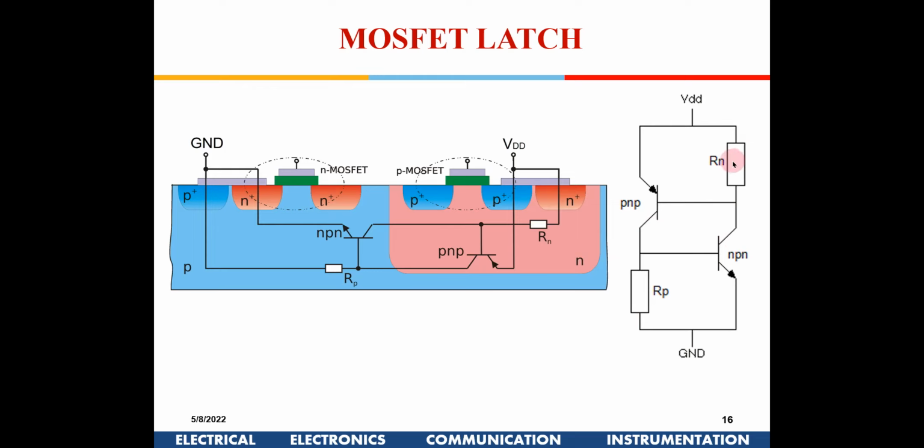Okay, so what happens is, suppose a small leakage current flows here. This voltage will drop here because of this RN. So this is a PNP transistor. A voltage drop here will increase the bias across the base-emitter, so more current will flow here. That higher current will again flow through RP, and it will increase the potential here. This increase in voltage will again increase the current here. So you see a positive feedback network has been formed here. A small leakage current results in a voltage drop, which increases the current, which increases the voltage out here, which further increases the current. So now you can have a condition where it's a positive latch, and you can land up in a situation where a high current is flowing between VDD and ground.